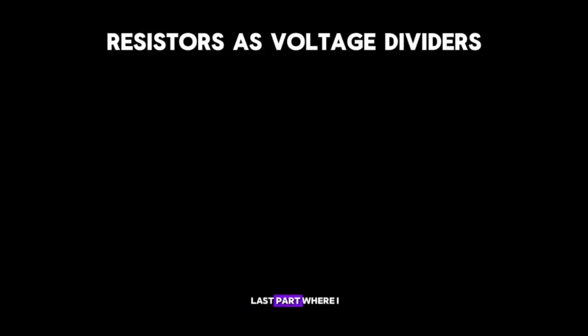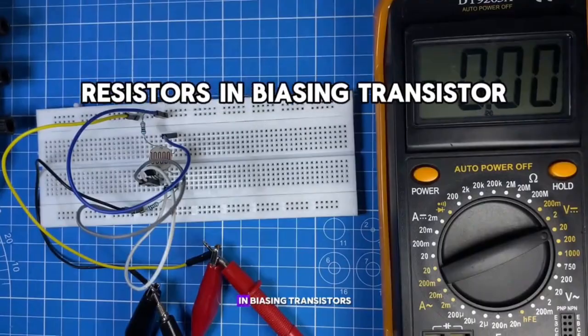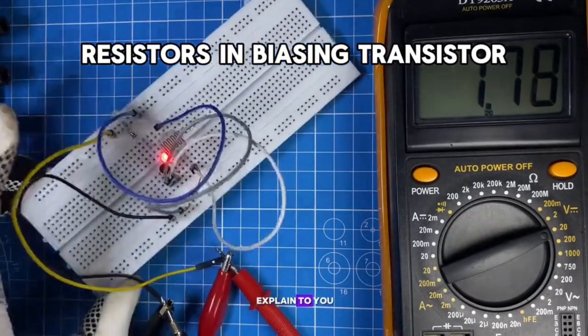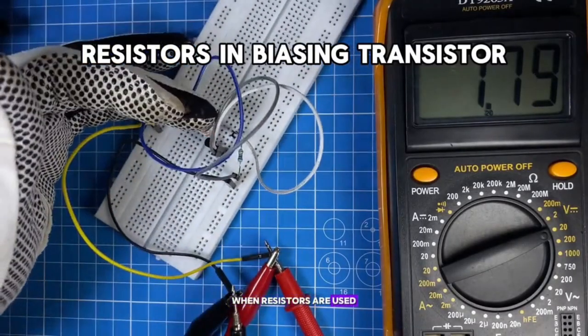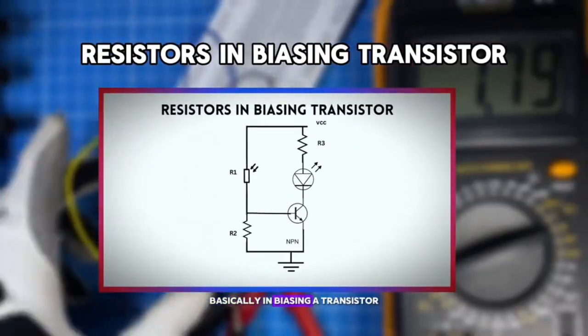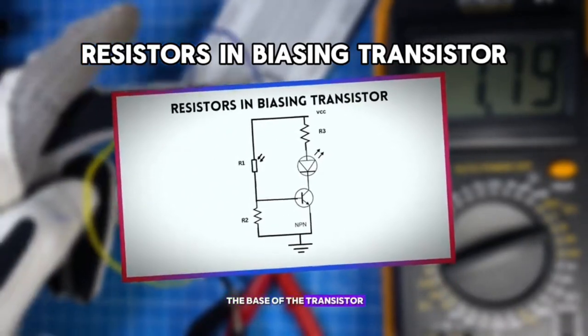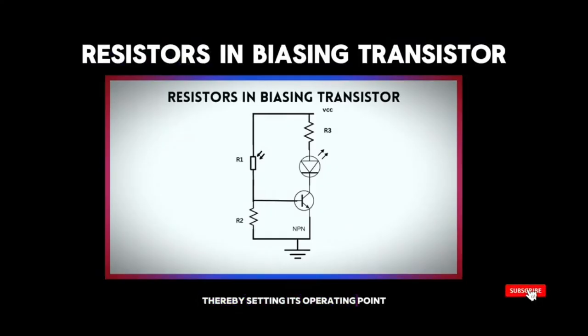So this is the last part where I am going to explain to you step by step and practically how resistors are used in biasing transistors. But before that, I believe it is also very important for me to explain to you what it means when resistors are used in biasing transistors. Basically, in biasing a transistor, resistors are used to control the voltage at the base of the transistor, thereby setting its operating point and determining how much current flows through the transistor. They act as a voltage divider to provide a stable and precise bias voltage to the base, minimizing the impact of variations in the transistor's beta value and temperature changes.